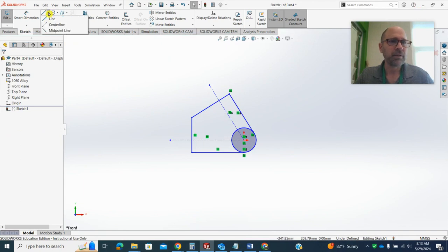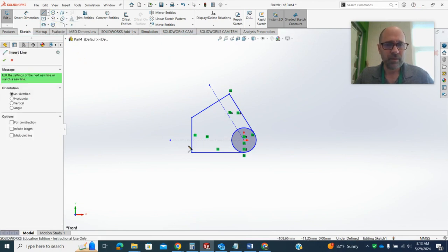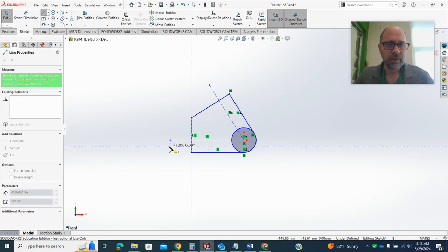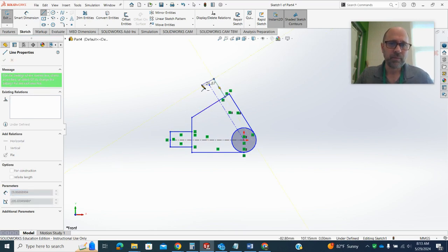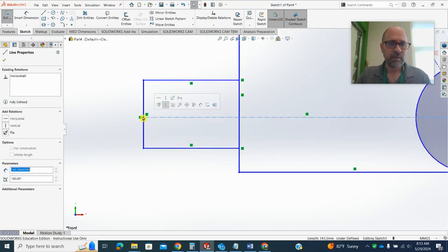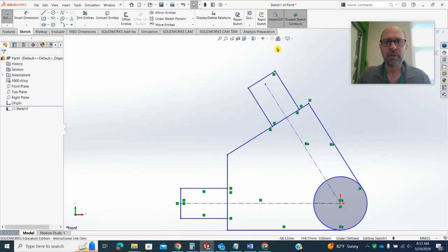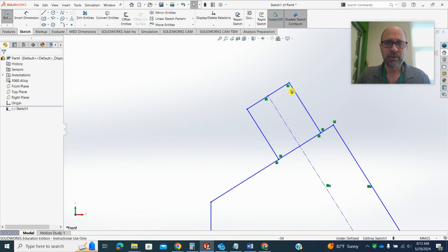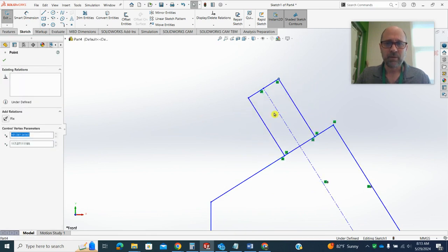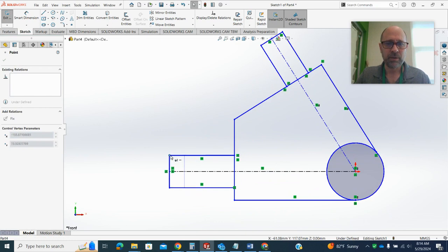I'm now going to sketch these tabs. And really what I want is the end point of the center line to be the midpoint of this little rectangular tab. So I'm going to move things to make that happen. So actually I can left click, control, left click, make midpoint. I'm going to do the same thing over here. Make midpoint. Okay, so now those should stay symmetric. All right, and I'll wiggle this, make sure it is. Okay.